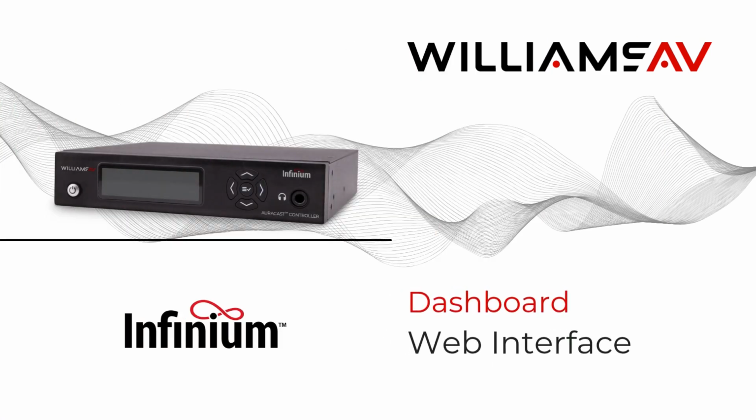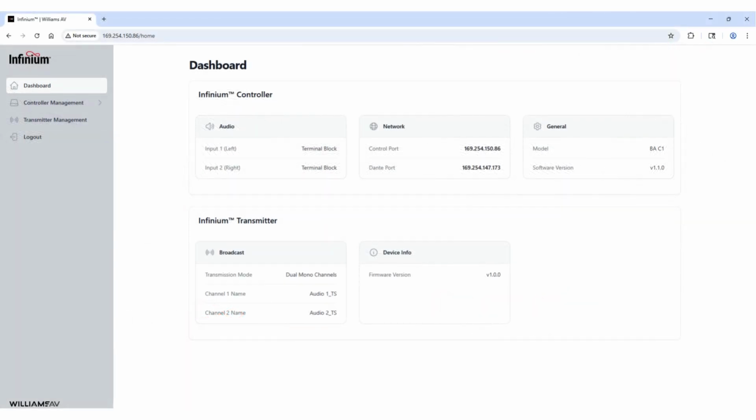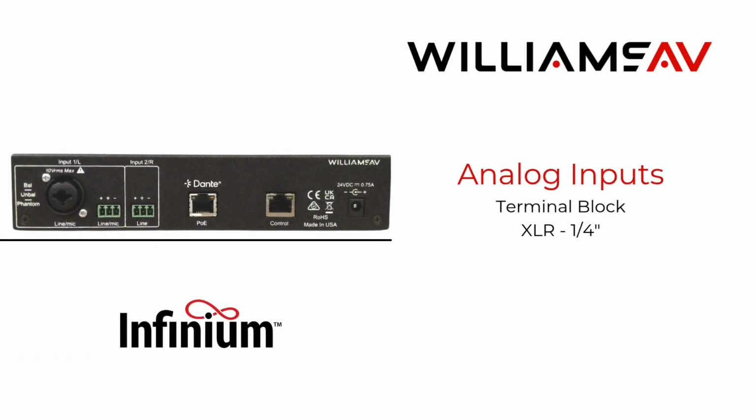The dashboard shows the overall status of the controller and transmitter units. Under the Controllers section, under Audio, this displays which input is active: Dante, a combination XLR or quarter-inch jack, or terminal blocks, commonly referred to as Phoenix blocks, and finally, a test tone. Note here, the terminal blocks and XLR jack support balanced line level, unbalanced line level, microphone level, and phantom-powered microphone level. The test tone is a 1 kHz sine wave audio signal.